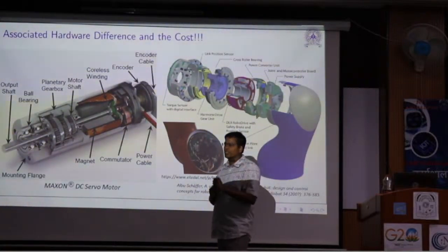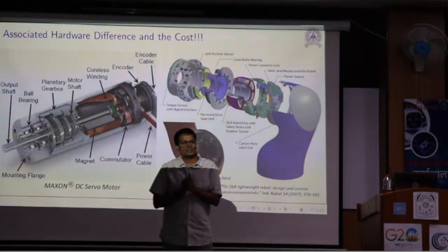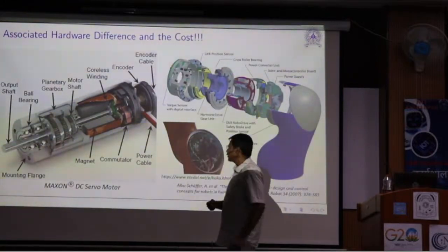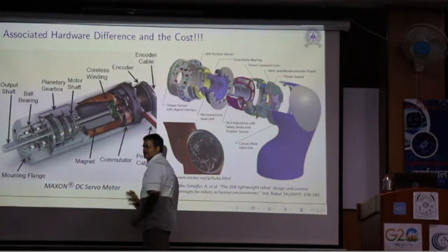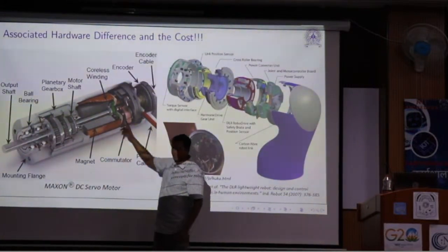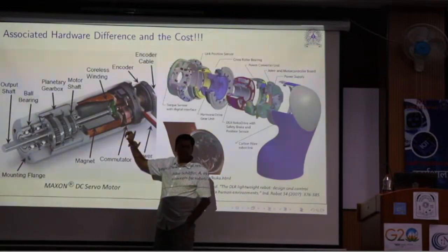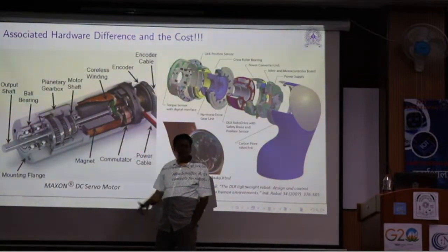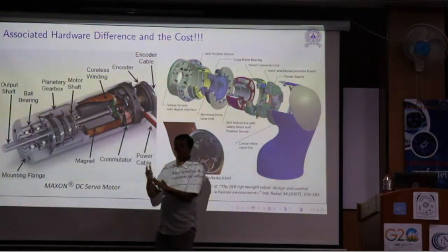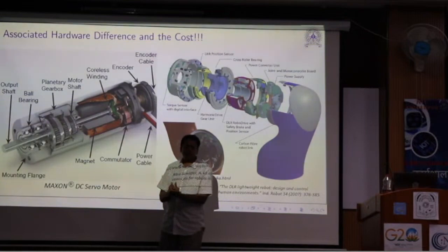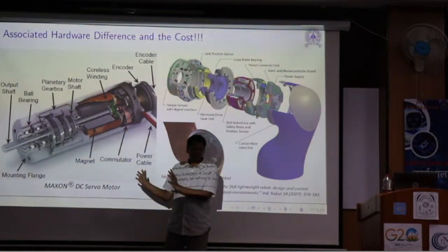But it will give you some sense of angle so that you can take feedback of an angle. So outside of this, you need to have a circuit which can power this device to run in a particular direction, to accept the command and then compare the angular values and stop whenever required based on your PID controller or whatever. Right?